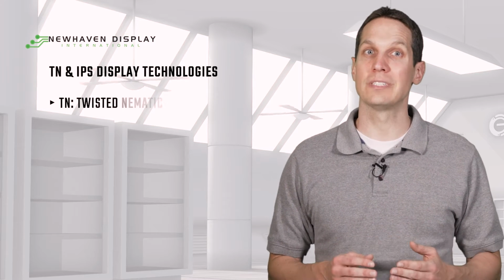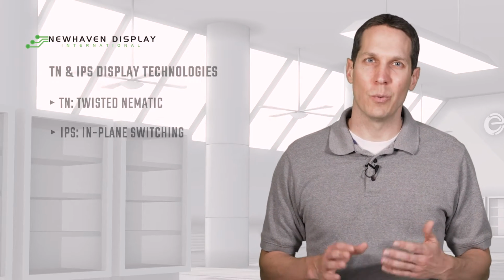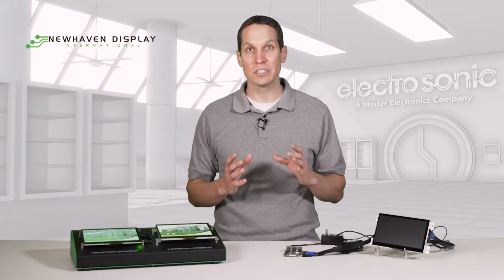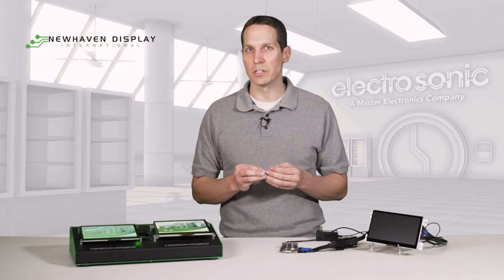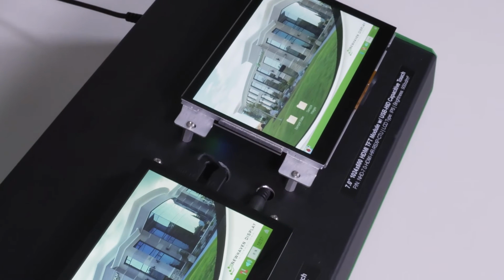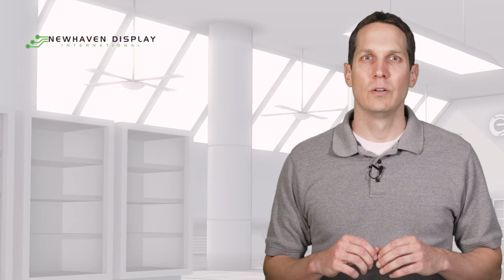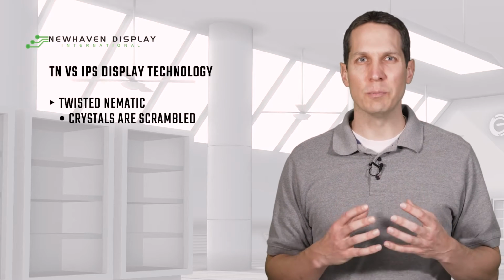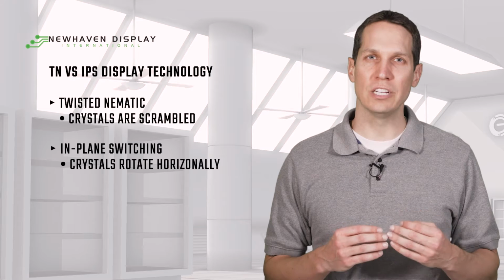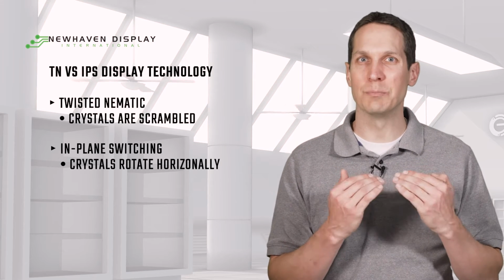While there are a lot of different types of technologies driving displays, we're going to focus on the TN, or twisted nematic, and the IPS, or in-plane switching, versions. While similar in that both of these displays use electric fields to control liquid crystal molecules, blocking or allowing light to pass as needed, the arrangement of these liquid crystals and the placement of the electrodes differ between the technologies. With TN, these crystals are more scrambled, while IPS uses a unique arrangement that generates an electric field that causes the crystals to rotate horizontally in plane.